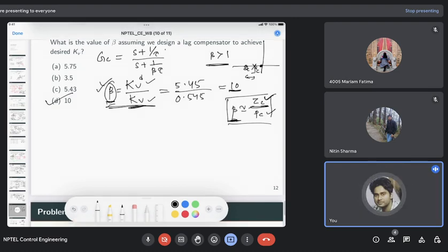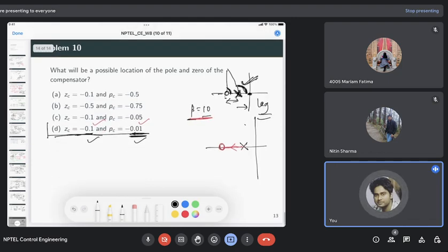So then we also have the liberty of choosing the zero and pole of this compensator. But again, after choosing them, you have to verify whether the angle contribution from them is very small or not. That can be verified using simulation in MATLAB. You just verify the transient response, or verify the root locus by plotting it, to see whether your desired pole locations are shifted much or not.